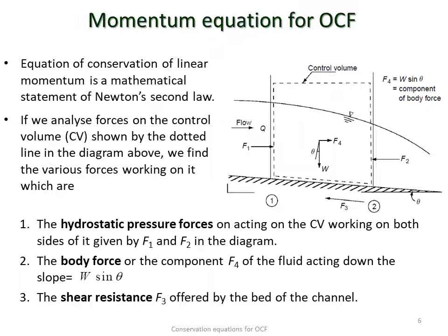So these three are surface forces working on the control volume, and the main driving force of flow, which is actually the body force, is given by the component of the weight of the fluid working in the longitudinal direction down the slope.